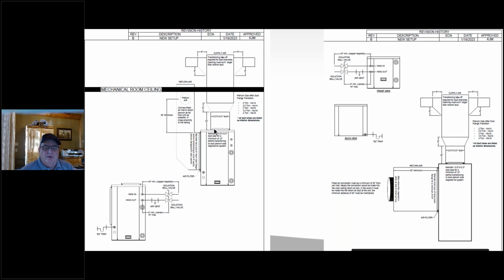But one thing that a lot of people do here is they make your plenum the same size as the cabinet, and it's not the best way to do it, especially with ECM blower motors. So this should always be maintained at least a 12-inch or more, close to the blower opening size, and then transition to your plenum a lot bigger. This is very important on the operation of ECM fan motors. So at your convenience, you can expand on these, make them larger, and see. Got some suggestions here for some of these units that we have, a couple different design ideas. So take a look at them and get some ideas.